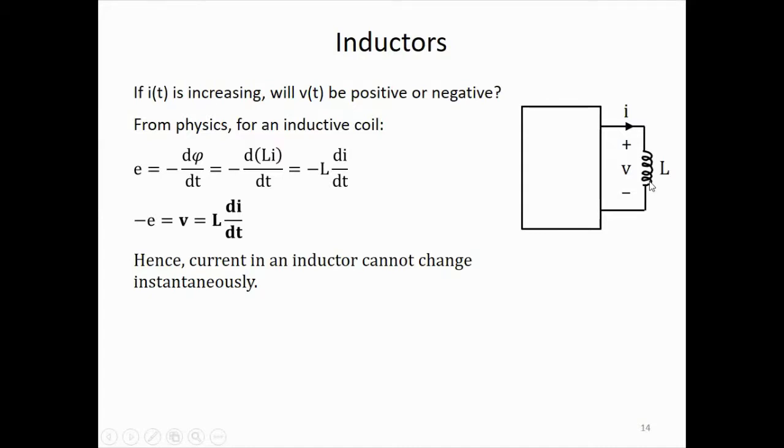Whenever a current is changing in an inductor, you know from, I think, Lenz's law, or Faraday's law, one of those laws, I never remember which one. I think it is Lenz's law that says that whenever one tries to change the current in an inductor, it induces an EMF that opposes that change. And the mathematics of this is that induced EMF is given by minus d phi dt, where phi is the flux enclosed by the inductor, and phi can be written as L times I, where L is the inductance of the coil and I is the current flowing through the coil.